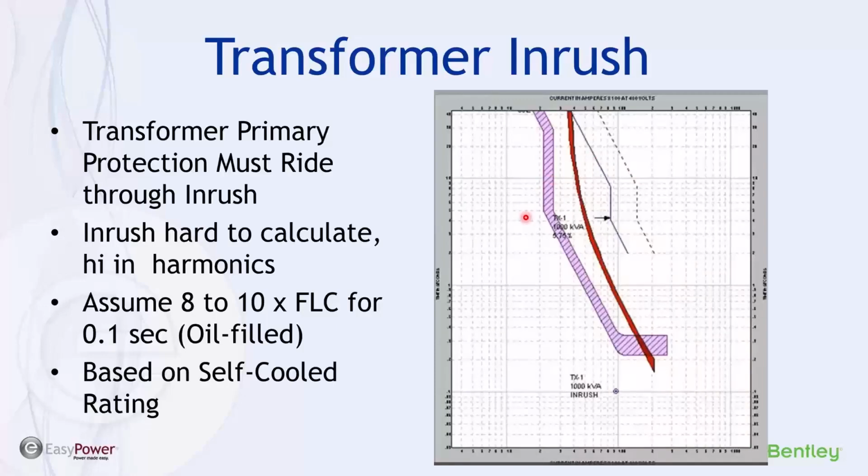And that's a good way to, in other words, the lower the draw on the transformer, the better we've extended the life. So temperature and time both affect the capacity utilization. And so the answer is, yeah, potentially that's one way to get there, but you do end up with higher current potential on a fault because of the extra capacity on the transformer. So it's something you have to pay for at some point in the design, but overall the ability to extend the life of the transformer and reduce the service aspect can be substantial.